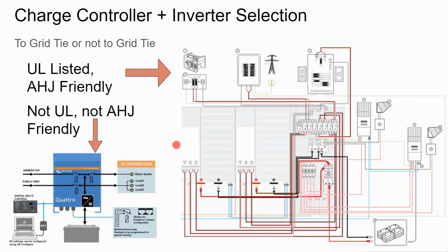What I would say is there are certain off-grid inverters that have a lot of this switchgear stuff already built into it. So say, for example, a one-way grid assist inverter that is not capable of outflowing onto the grid. So whether it comes from a generator or it comes from the grid, there's a transfer switch already inside an off-grid inverter that says we're either going to be flowing through the grid or flowing through the generator.